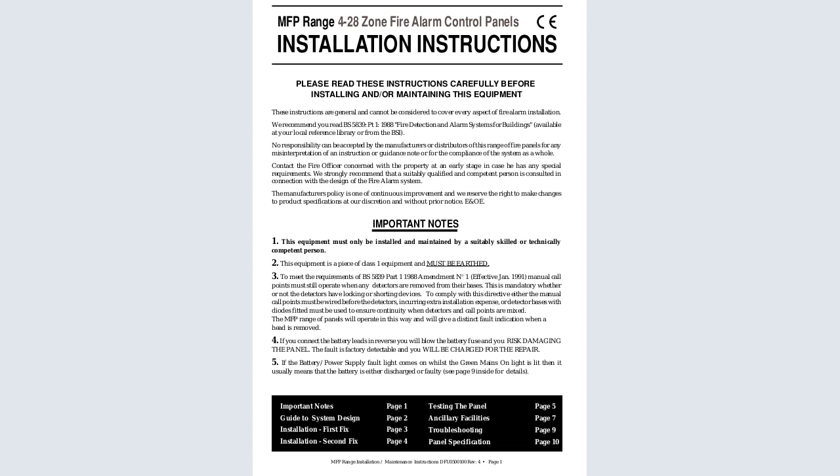To comply, either manual call points must be wired before the detectors, incurring extra installation expense, or a detector base with diodes fitted must be used to ensure continuity when detectors and call points are mixed. The MFP range of panels will operate in this way and will give a distinct fault indication when a head is removed.